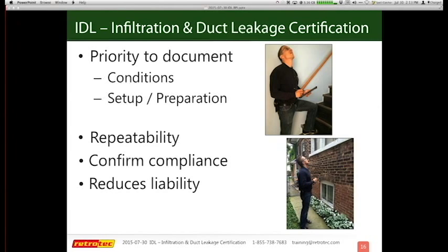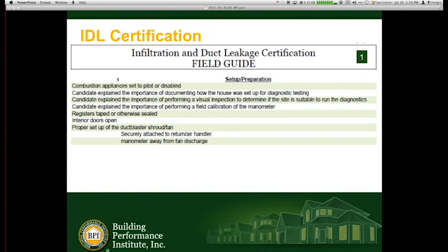A lot of people will show up, go inside, and start setting up their test. I do have some things about the blower door and places you should check. But in general, you want to make sure you evaluate the outside and inside, and for the blower door, the crawl space and attic, and a few other high priority areas that some people just assume are in acceptable conditions.